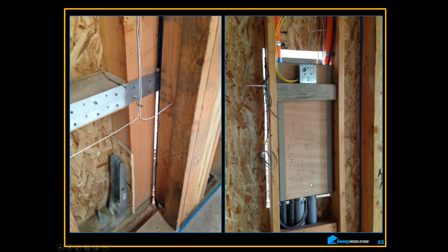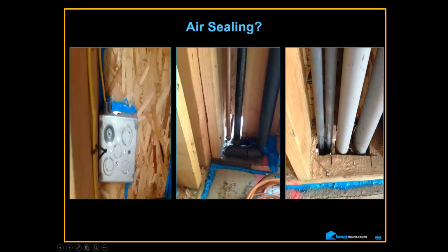They've got to take this whole thing apart in order to put another panel over the top, you know, dry OSB, and then put this back in again and cut the hole properly. Same thing here. I mean, here's an electrical box. So they sealed around the box. Look at the hole in here. And look at all these holes. It's absolutely useless. This guy is amazing.